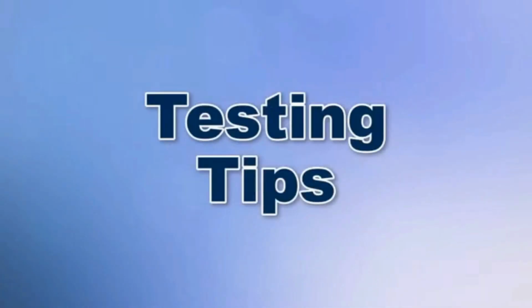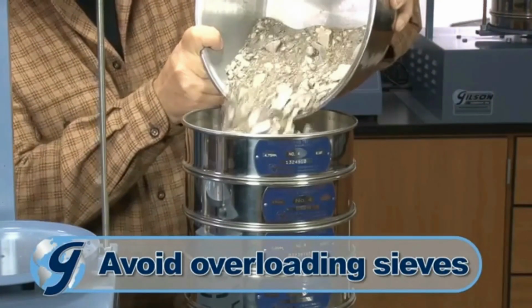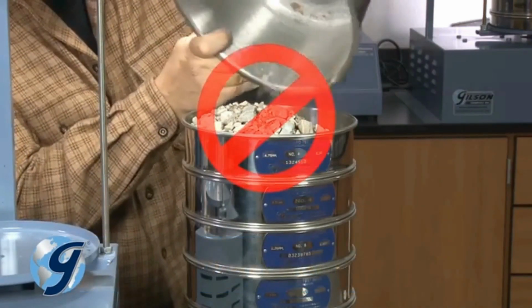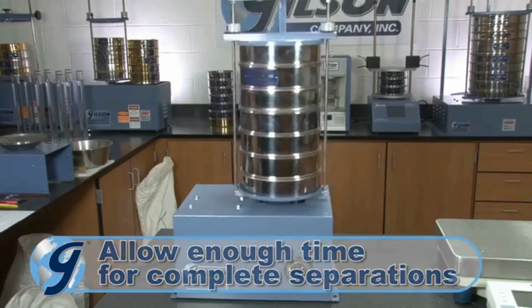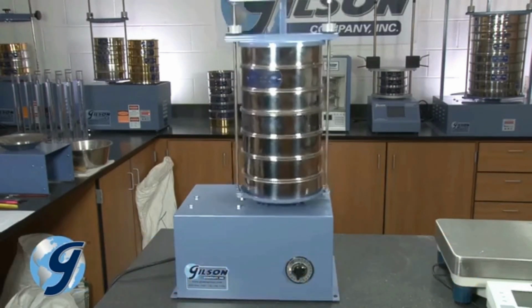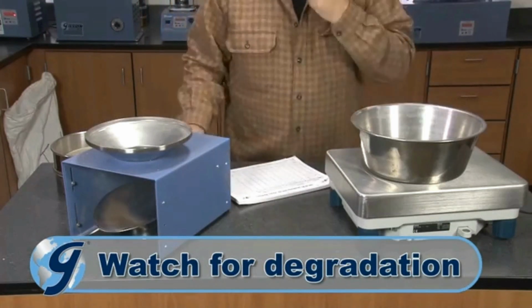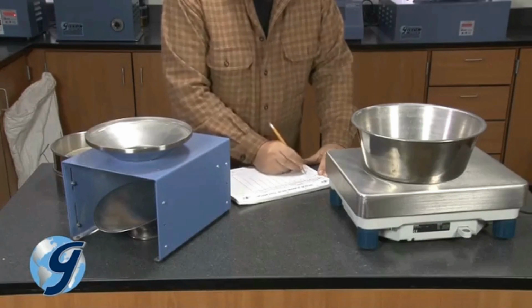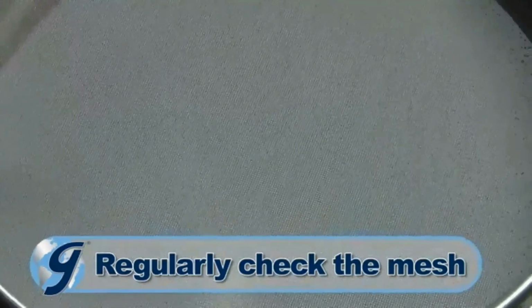Follow these tips for accurate and repeatable particle determinations. Avoid overloading sieves. Total material retained on a sieve at completion should be less than 1 to 2 layers deep. Allow enough time on a sieve shaker or testing screen for complete separations. Watch for degradation. Some brittle or friable materials can break apart during separation process, leading to inaccurate results. And regularly check the mesh for wear, tears, or distorted openings, since this can bias test results.